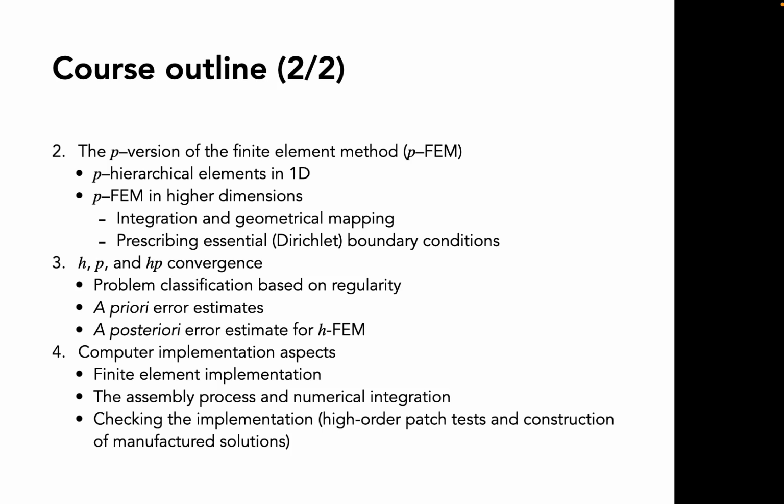So we're going to look at a priori error estimates. In essence, what we're going to do is to learn theoretically how the finite element method converges when you refine the mesh or when you increase the polynomial interpolation, right? And we're going to do something called a posteriori error estimates, which, as I said, you can actually use to estimate the value of the exact strain energy for your problem, even if you don't have an exact solution. And this is very powerful, because if you have an estimate of the exact strain energy, then you know what you have to do to improve on the solution, okay?